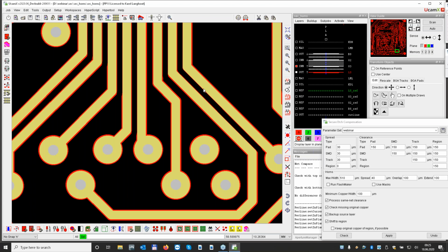But if you remember the picture that we had before in the presentation, actually this etchant that we are having is flowing a lot on these big areas. So here you have a lot of turmoil going on, and actually there will be more etching done on this side than on this side, because here the etchant cannot flow that fast.